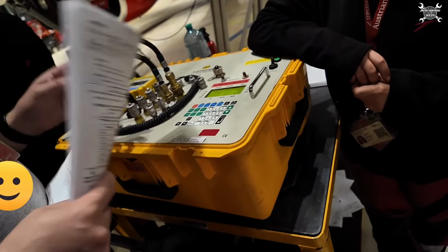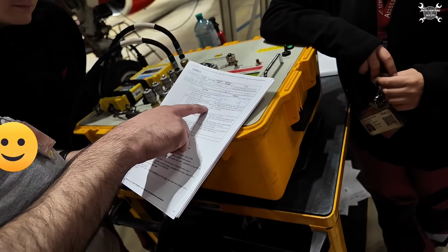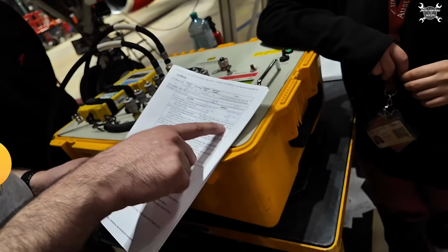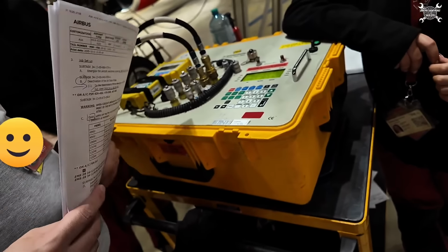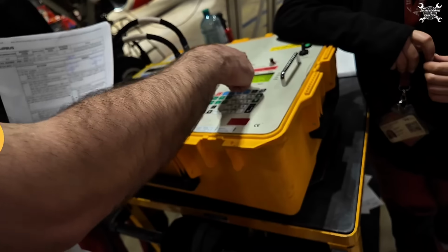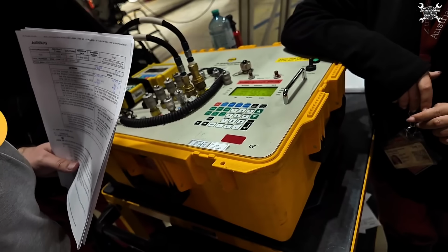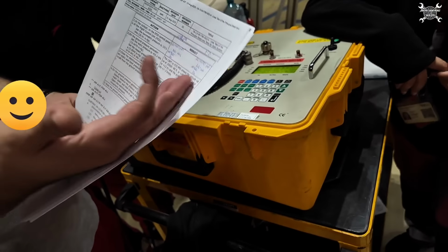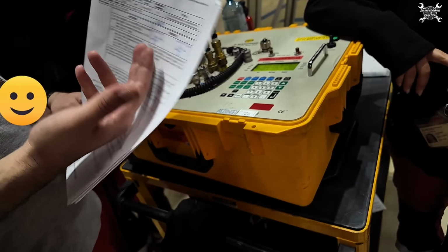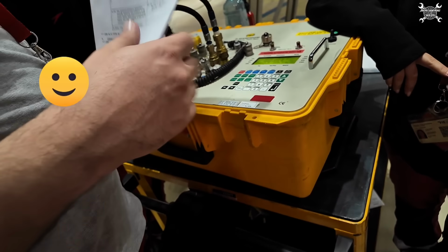Makes sense, and it was nicely shown. Because when you put this pressure here, and you get this one here, this means that the air data module is okay. Okay. When I put here 20,000, it's not 20,000 upstairs. Yeah, because the pressure is not correct. The leak is okay. But when I put the pressure, I know that also the air data module is okay.